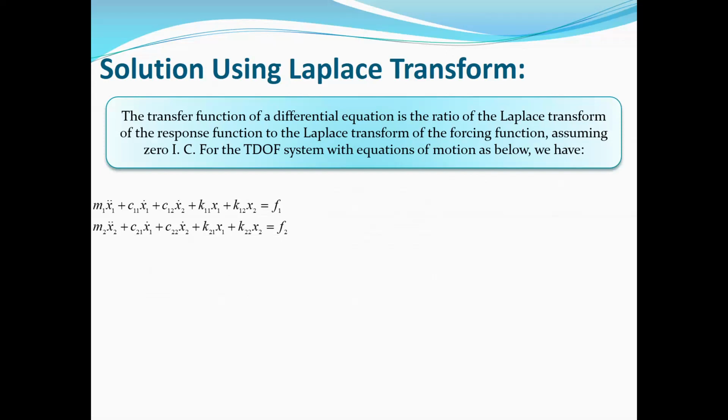Another method to obtain the response of systems subjected to, in SDOF systems, you saw that when we deal with a system which is subjected to a non-periodic or an arbitrary external force, when we cannot extract any harmonic form for the external force, usually we use other methods. In the SDOF system, we use, for example, convolution integral and Laplace transform.